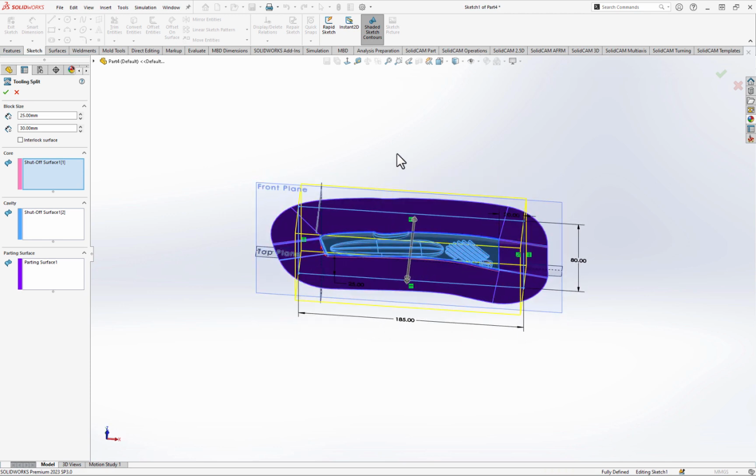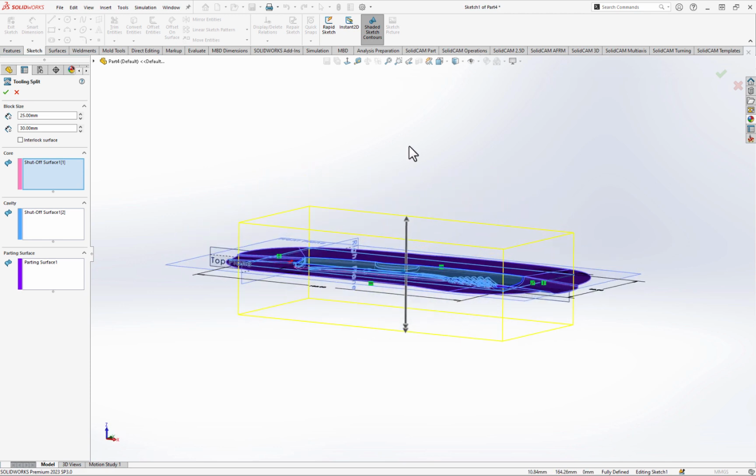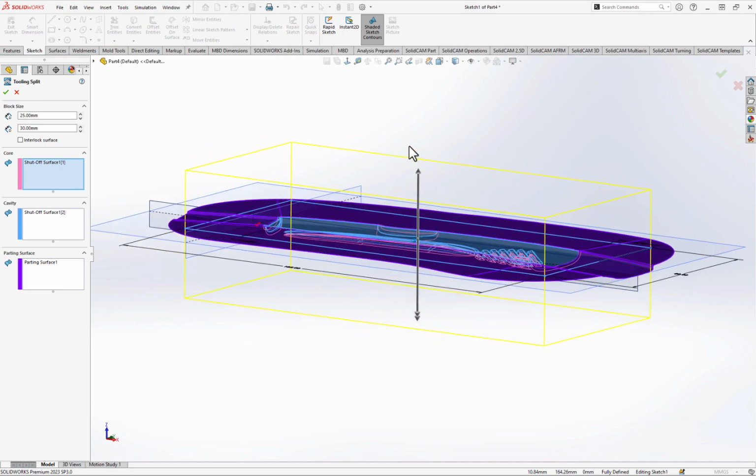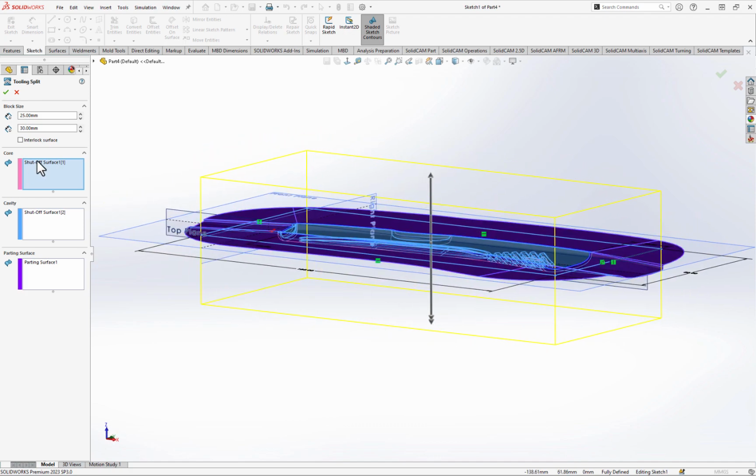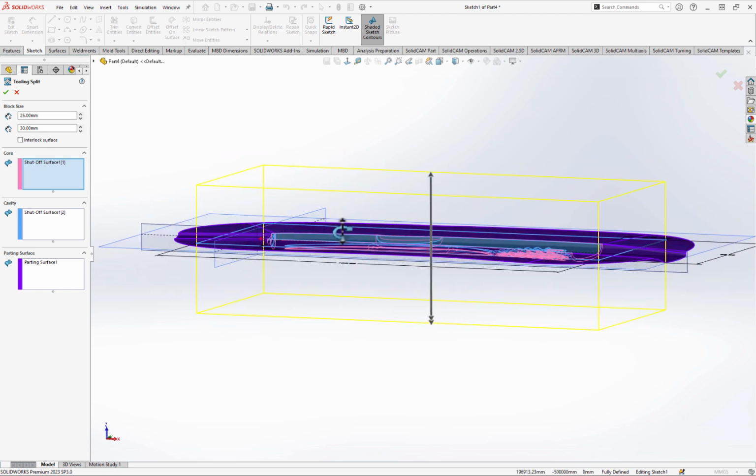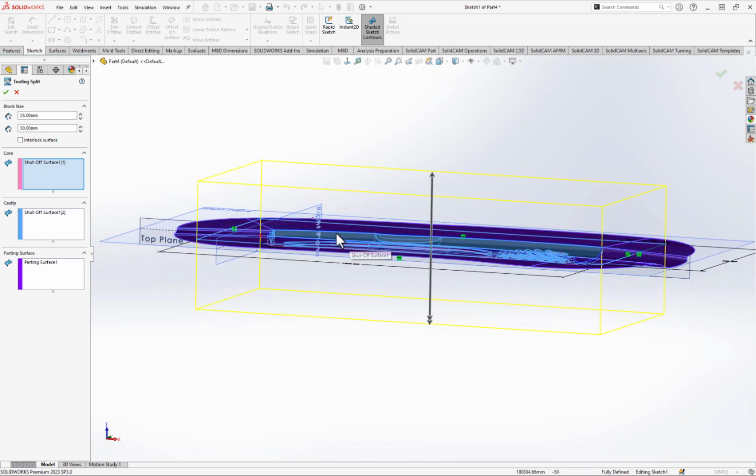and then you'll need to rotate your view to see what's going on and appreciate what's going on. So from that sketch plane, the system is going to extrude essentially in direction 1. So I believe this is the upwards direction. Let's adjust it. Yep, so that's direction 1. That will create our core half of the mold. So that has to be deep enough to have enough mold material there to accommodate that core, and then we'll see later to accommodate some cooling channels and some fixture holes and things like that.